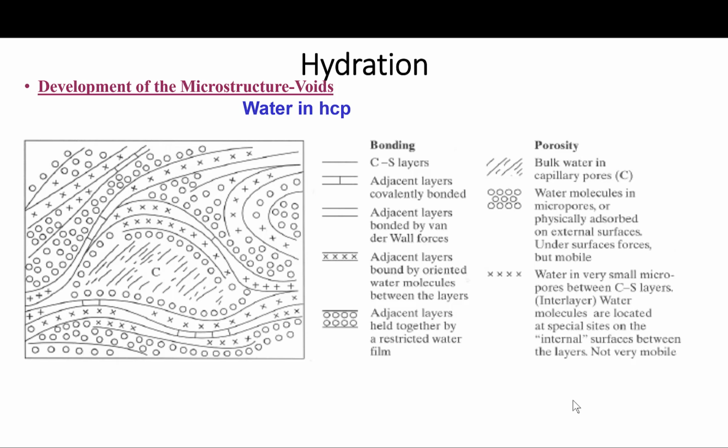But depending on the environmental humidity and the porosity of the paste, the untreated cement paste is capable of holding a large amount of water. Like the solid and the void phases discussed above, water can exist in the hydrated cement paste in many forms. So the classification of the water into several types is based on the degree of difficulty or ease with which the water can be removed from the hydrated cement paste.